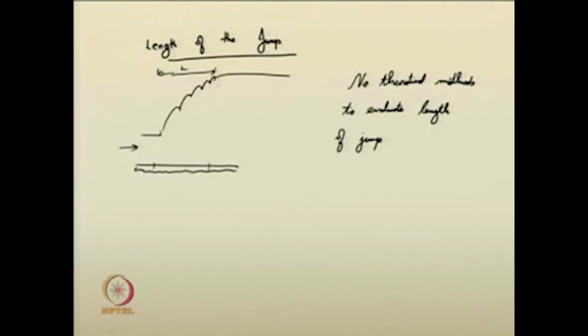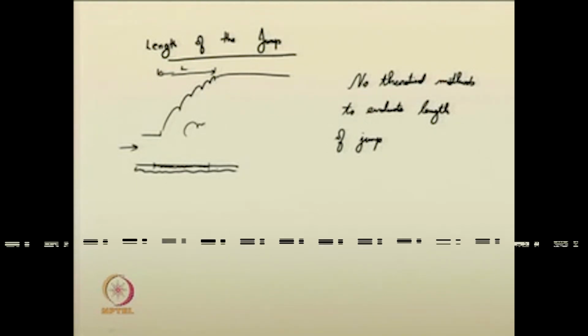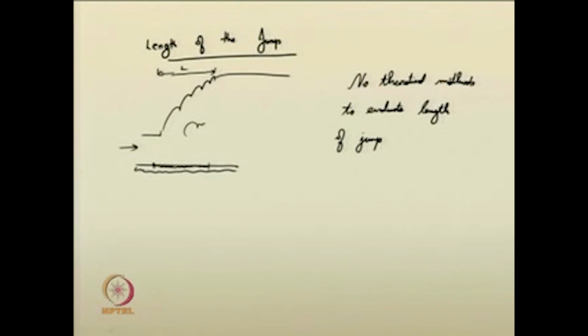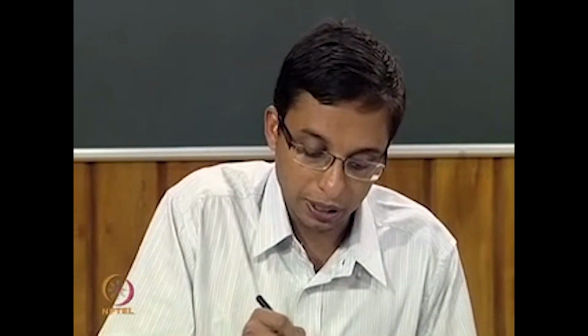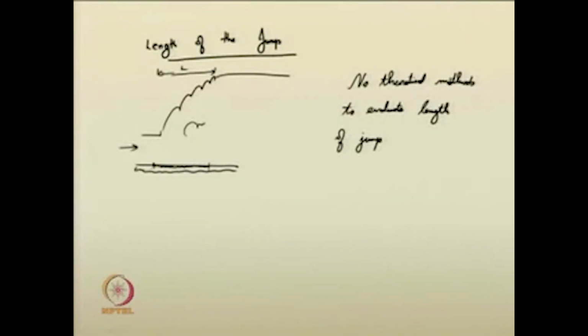You are now going to create a hydraulic jump to dissipate the energy, which we will discuss later. But due to this high impact velocity, high jet flow, there could be scouring. So, for how much length you need to incorporate protection in the channel bed, for that you need to understand the length of the jump. Up to this much region you can give a proper, better protection compared to other regions. That way you can economize your channel beds.